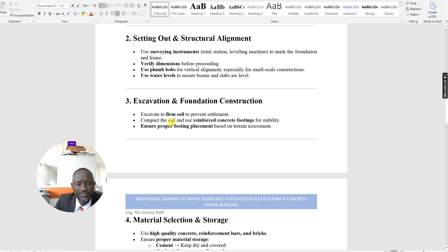Because you still need the surveyor to work with the landscape engineer to handle what they call external drainage, because you need to locate those inspection chambers, the manholes, the septic tank. All those facilities do require level checks and setting out. So we need to have all those guys in place.